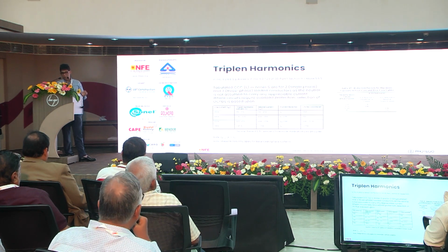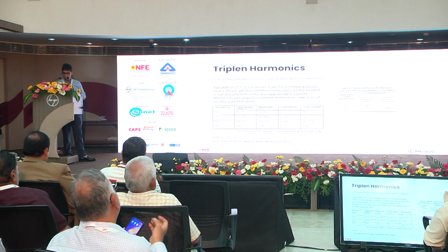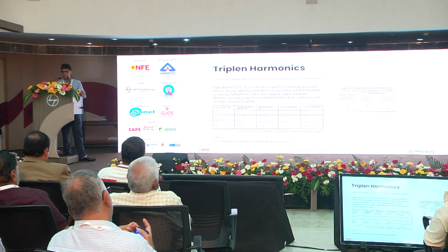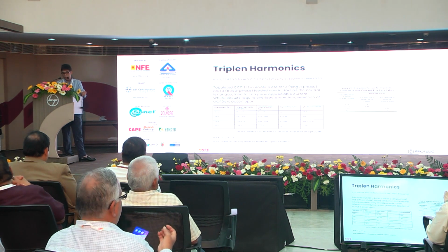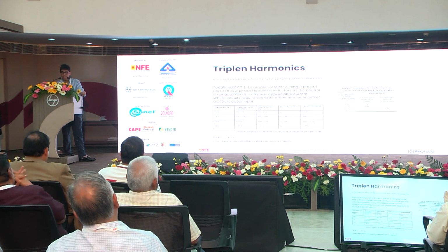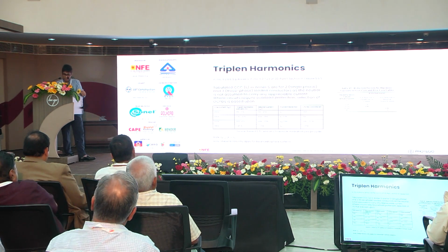And up to 15%, we do not need to worry about making any additional allowances for the harmonics, because this is way within the current carrying capacity of the neutral. But this is where it starts getting interesting. If you have 15 to 33% triplen harmonics, then 45 to 99 amps. And you're reaching 99 amps for a 100 amp rated circuit. So then derating is required.